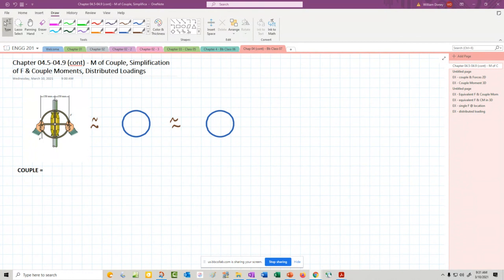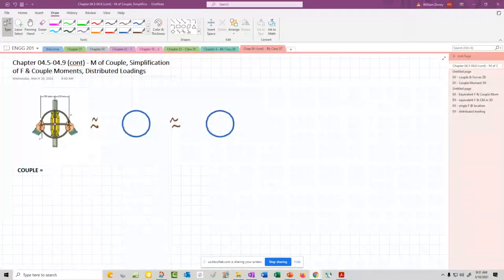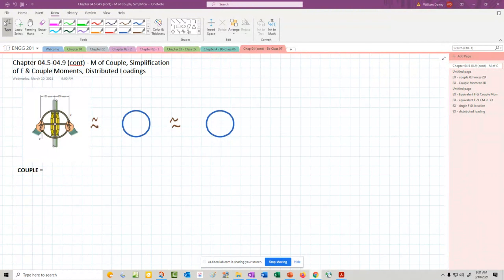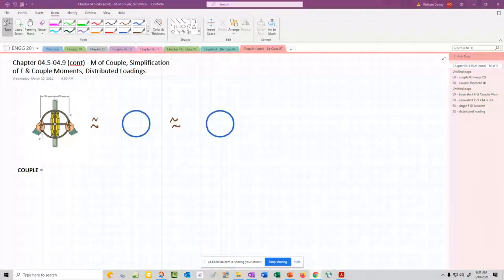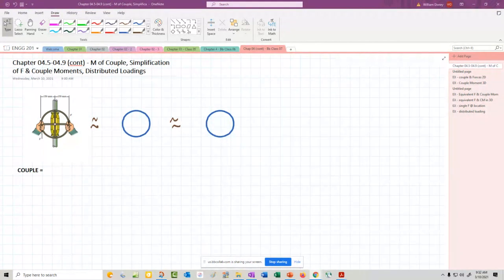So in the second unit, we're looking at different moments. We found moments about a point in 2D. Then we found moments about an axis. And then we found moments about a specified line using the triple scalar product, basically taking the R cross F moment and dotting it with the line of interest. And from that, we could find the moment in Cartesian vector form, and we could also find the direction cosines alpha, beta, and gamma for that moment.